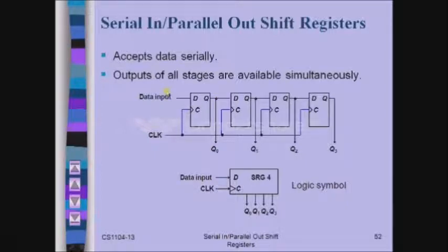The third input that I am going to give is 0. Now this is processed by the first flip-flop, therefore the output at Q0 would be 0, and Q1 would be 1 and Q2 would be 1. Now during the fourth rising edge, if I am giving the input as 0, then the output would be 0 at Q0, 0 at Q1, and Q2 and Q3 would be 1s. So this is how we are going to shift the data parallelly. This is serial in, parallel out.